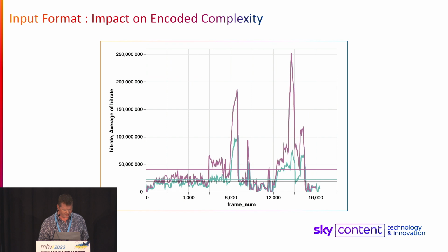So that I don't run over time, we also talk quite a lot about the input format and the differences between a baseband SDI input and the impact that has versus mezzanine. In a nutshell, what we're getting at here is that signal preconditioning, especially before distribution encoders, is particularly important. You get a very, very different characteristic from using uncompressed SDI versus mezzanine encoding before the distribution encoder.